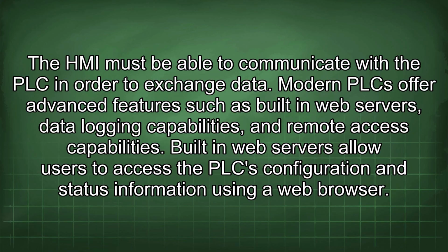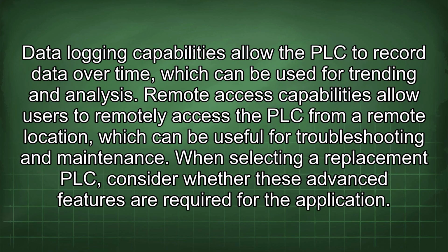Modern PLCs offer advanced features such as built-in web servers, data logging capabilities, and remote access capabilities. Built-in web servers allow users to access the PLC configuration and status information using a web browser. Data logging capabilities allow the PLC to record data over time, which can be used for trending and analysis.